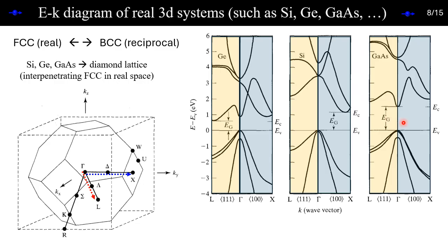And importantly, remember in the first class we said there are also alloys. We can have gallium arsenide, gallium nitride, indium gallium. You can dope with something, or you can alloy. With all these mechanisms, essentially you can tune the bandgap. Whenever you tune the bandgap, the radiated energy is different. Energy means the frequency, which means the wavelength. So depending on the band gap, you will have different types of light.